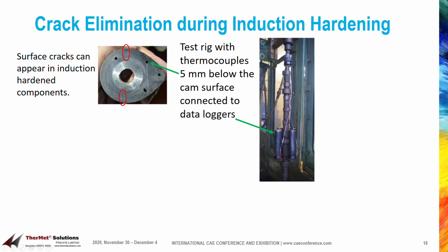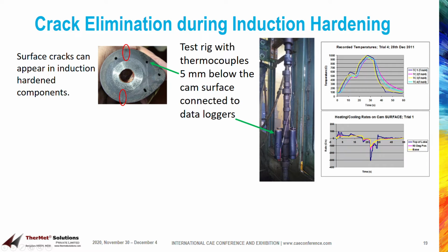4 thermocouples connected to data loggers were inserted at strategic locations 5 mm below the surface of one cam lobe. Time temperature data were recorded over one complete cycle of heating and quenching.